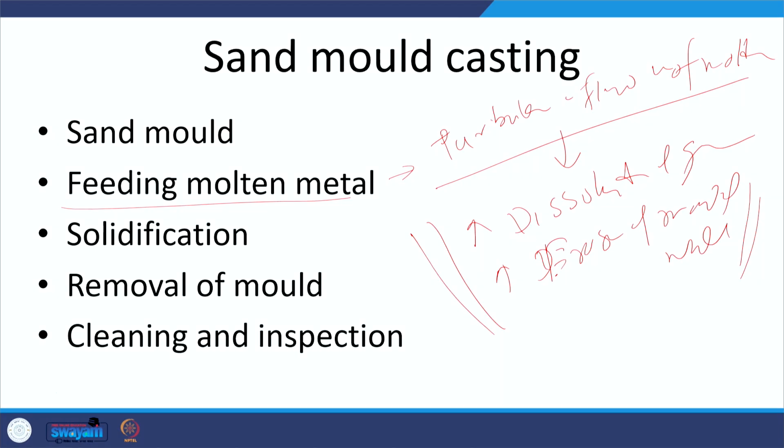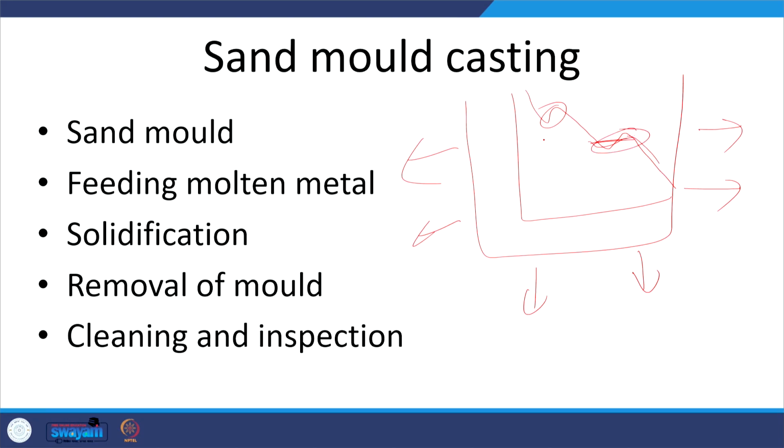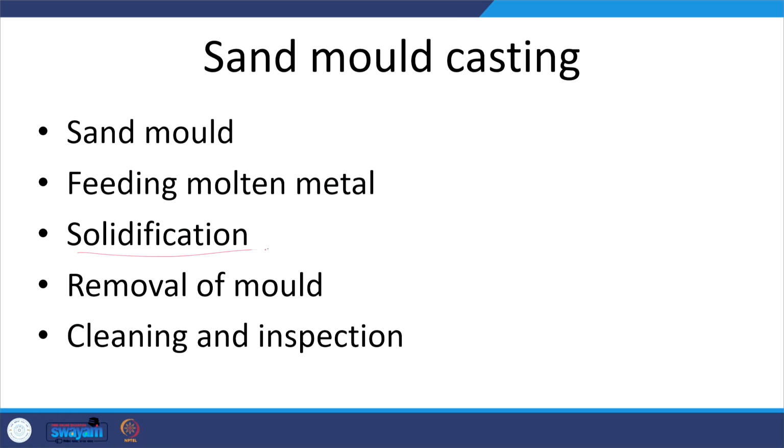Okay. So, as I said, since the solidification time is long due to the low thermal conductivity of the mold wall, it takes long to complete the solidification. Here solidification starts, here it ends. So this time from start to end is long in case of sand mold casting because of the low thermal conductivity and the low rate of heat transfer or dissipation from the molten metal to the mold wall. Once the solidification is completed, then the mold is broken.